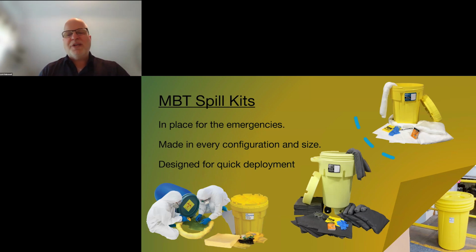You want to keep your spill kits full and ready to go in case something like a hydraulic line breaks or something. You have a big spill that you need to contain right away. You want to be sure those spill kits are full and up to date. Not a huge investment, but they're there for a reason. So check your spill kits.